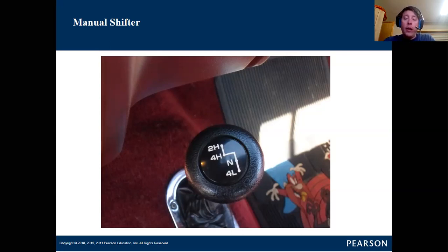So if we come in, let's say it's a 1 RPM input, we can have a 0.5 RPM output. That allows the transfer case to multiply the engine's torque even more. It's a way to cheat when you have a high load scenario. For example, you're at the boat launch, you're on somewhat slick surfaces already, you don't want high wheel speed, but you want high torque. You could place your pickup truck into 4 low while pulling your gigantic barge of a boat out of the water.